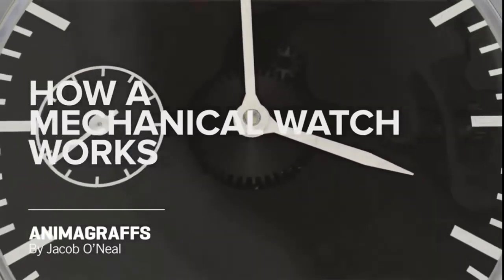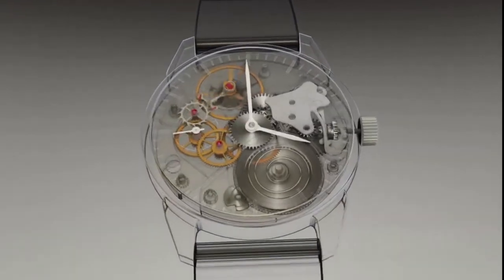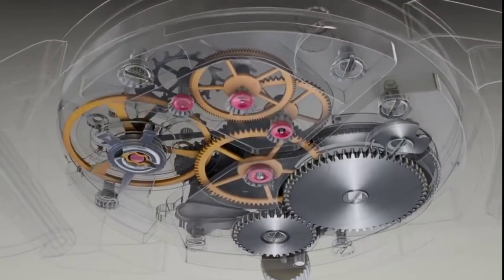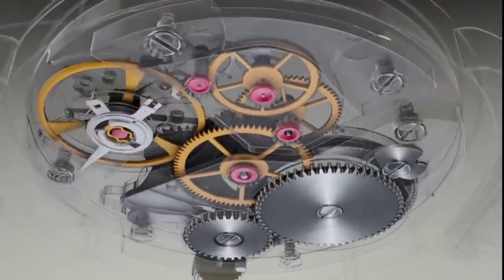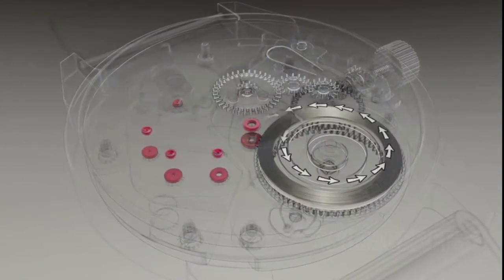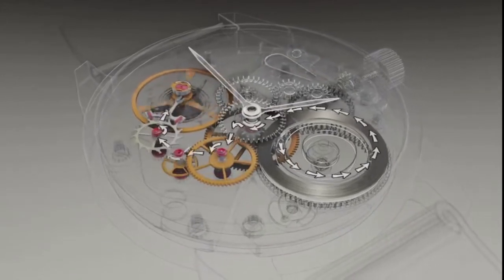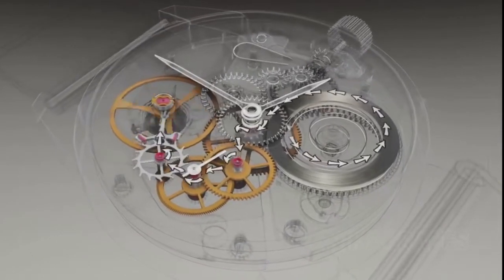I'm Jake O'Neill, creator of Animographs, and this is how a mechanical watch works. Watches have no battery, microchip, or circuitry. Watch parts are machined to near perfection at microscopic sizes and tolerances, and can produce accuracy within 2 to 3 seconds per day. Let's take a high-level view before diving into specific parts. Power is stored in the mainspring and released in reliable increments by the escapement assembly. The gears that connect the mainspring and escapement turn at various speeds, allowing the watch to tell time. Now let's look at each section in depth.